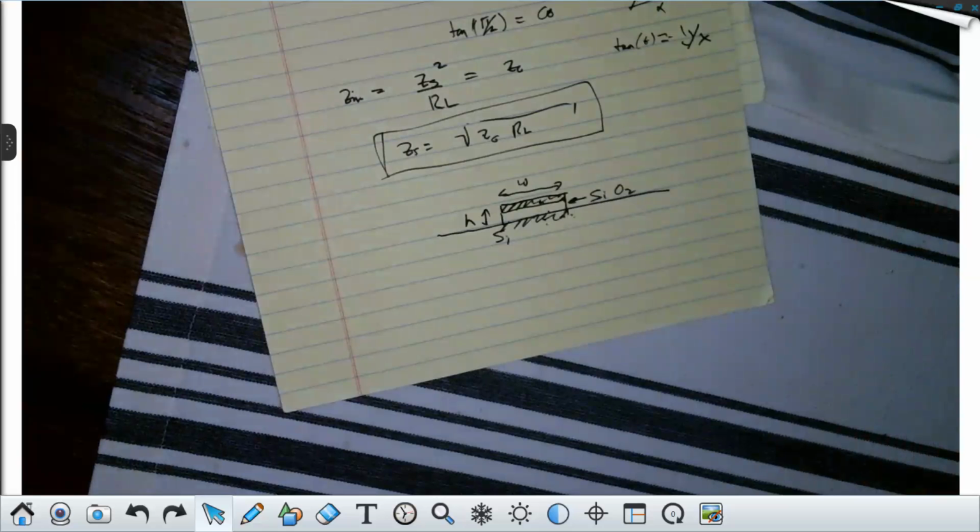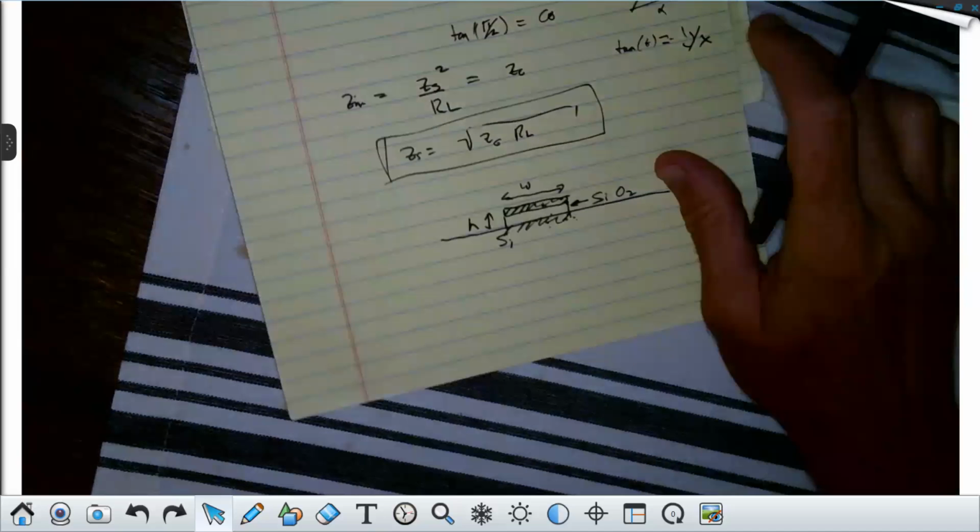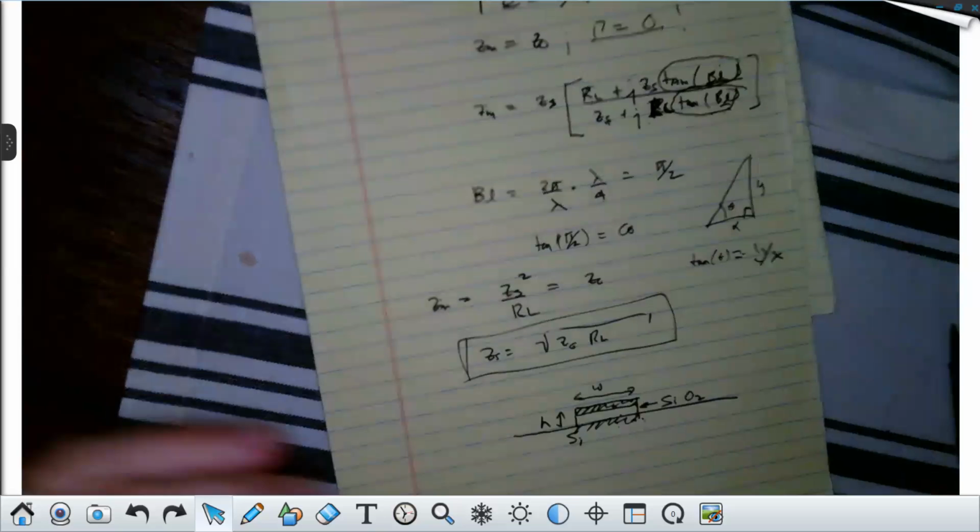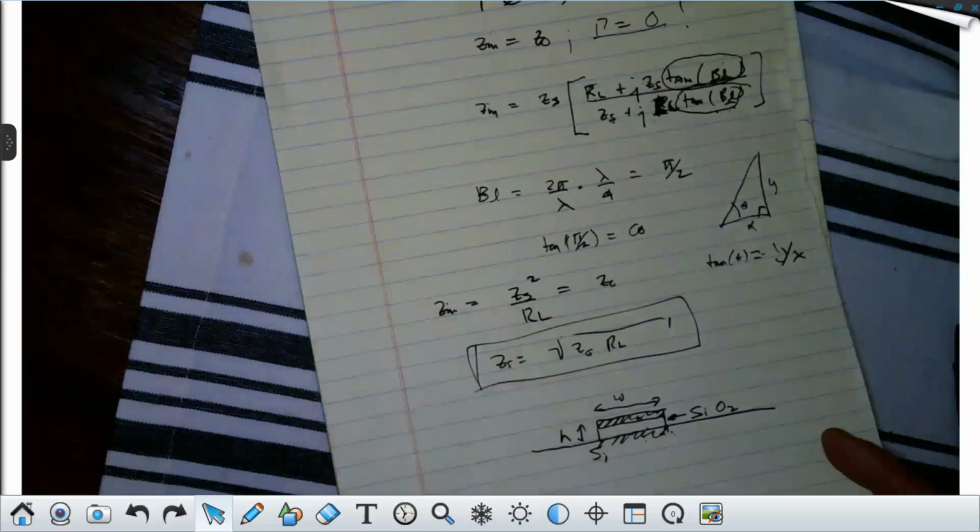Something else I'm going to mention: all the impedance matching that we're doing here only works when you're talking about a constant frequency. If there's a wide difference in frequency, say the center frequency of the signal moves like 30%, then all this impedance matching won't work. It has to be a signal with very little change in the center frequency. You need to be aware of that, because more and more these days we're talking about wideband signals with a lot of frequency components, and you can't use this for impedance matching. Okay, I wanted to cover that first.